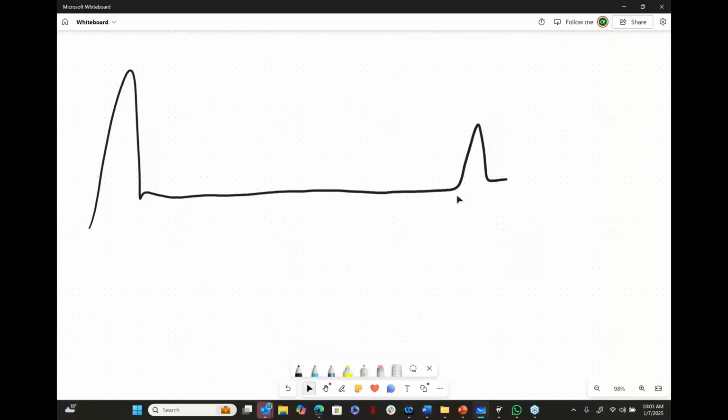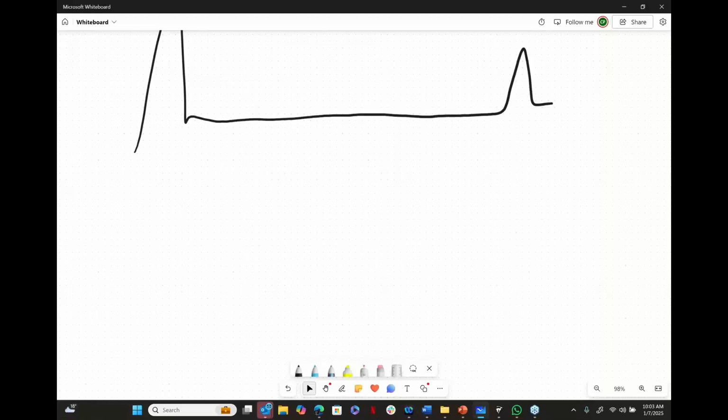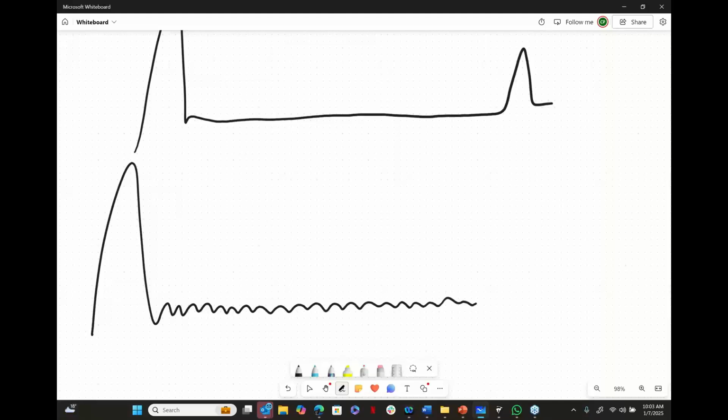When little shapes start to appear, that's when we start to analyze, well, what is that shape? And I'm always going to tell you, I want you to be more concerned with where it is, not necessarily what it is. I'll give you tips on how to figure out what it is. But the bottom line is, if the line is flat, that means there's nothing wrong with the cable until you start to really analyze it. When you increase your vertical gain, that begins to increase what I like to call the vertical volume of that line. So you're turning it up to see if you can see something that could be hiding in that line.